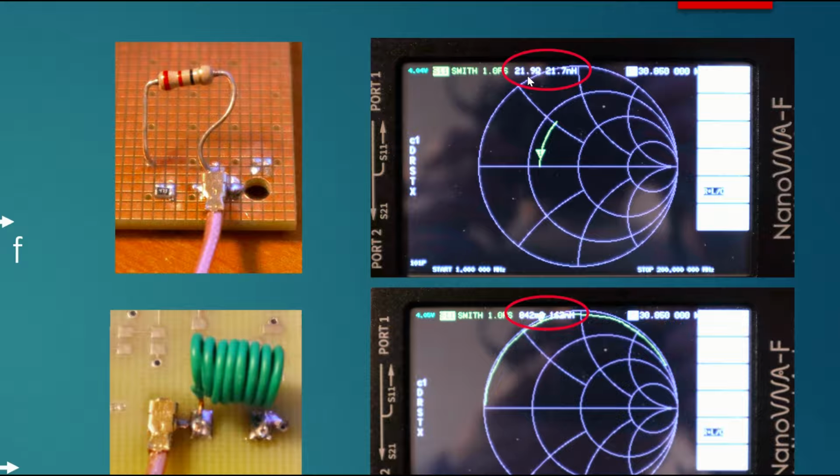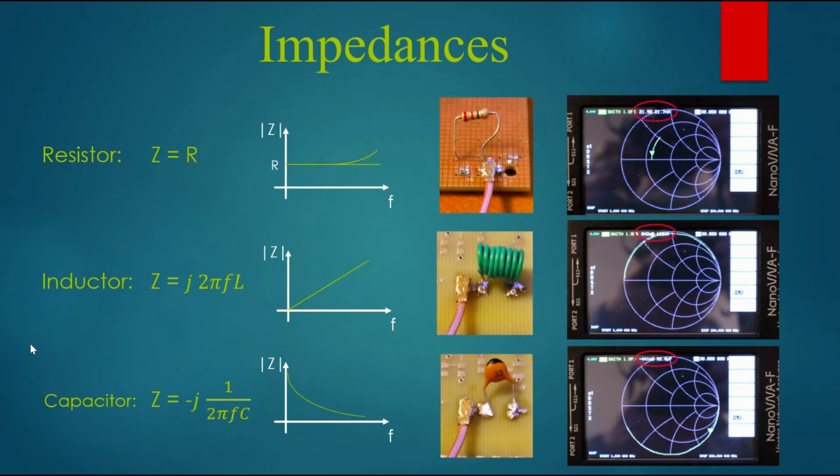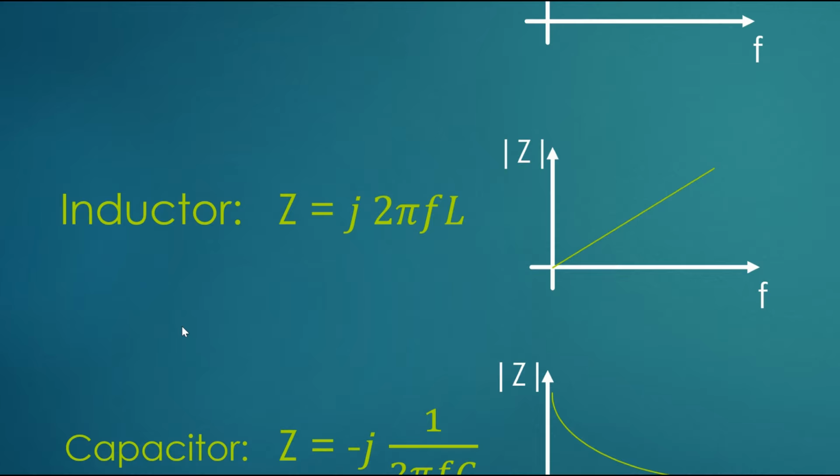It says basically 22 ohms and 22 nanohenries in series with 22 ohms resistive. So a resistor becomes a resistor in series with an inductor at sufficiently high frequencies. And we will have to deal with that. That's part of the radio arts, to understand how to deal with such issues. Resistors in reality are not always just simple resistors. Okay, an inductor and a capacitor, let's take a look at those.